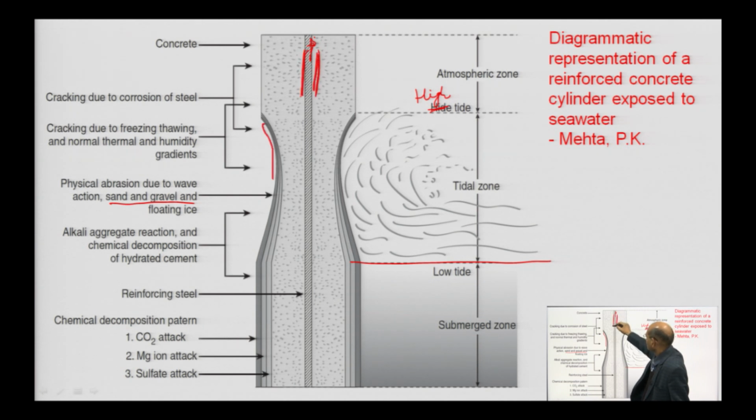And lastly, if the reinforcement gets corroded, its volume will increase. After the increase in volume, the structure will crack. Due to this, once again more ingress of oxygen, water and chloride will take place, and due to the penetration of these harmful ingredients, the rate of corrosion will increase. So, these are the actions we have observed, showing how this affects our concrete. Durability is directly related to permeability. If our concrete has been made with due consideration, then certainly it is not going to deteriorate, and it will serve its life.